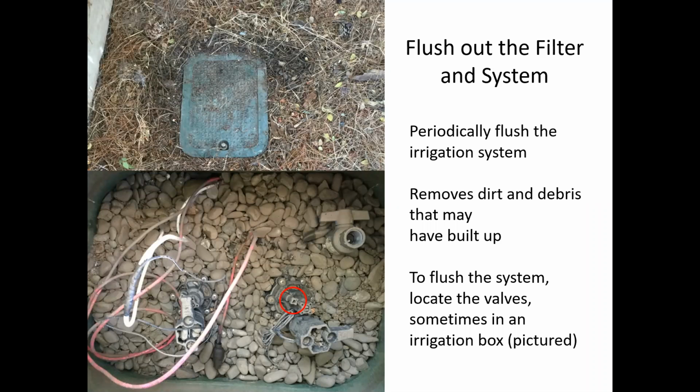So you've got some wires, and those wires are connected to your solenoids. And what the wires do is send an electric pulse to that solenoid to turn on. So it's connected to your controller and it's saying, hey, irrigation zone, wake up. And then below that is the actual valve, which gets opened by the solenoid.